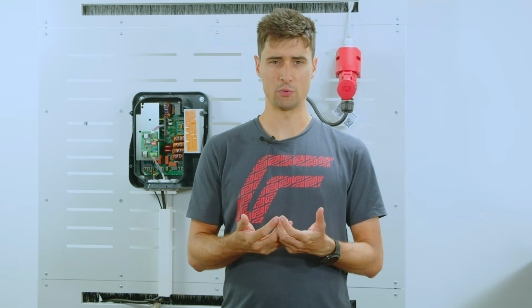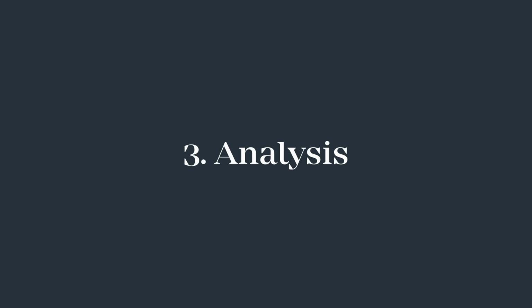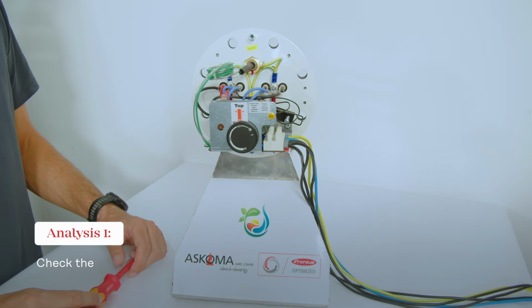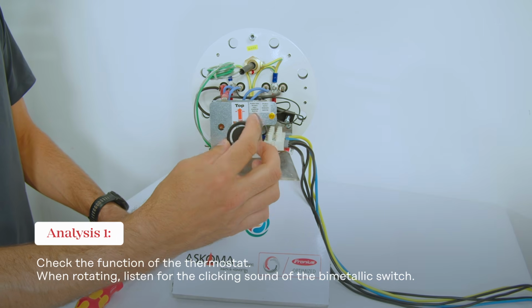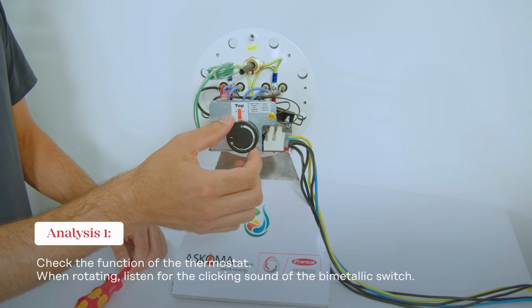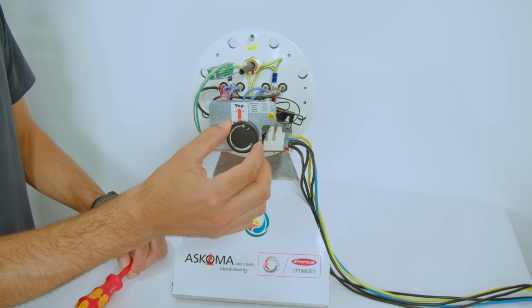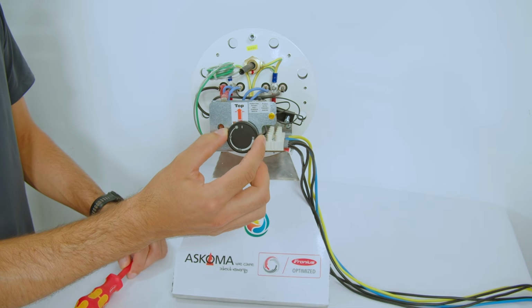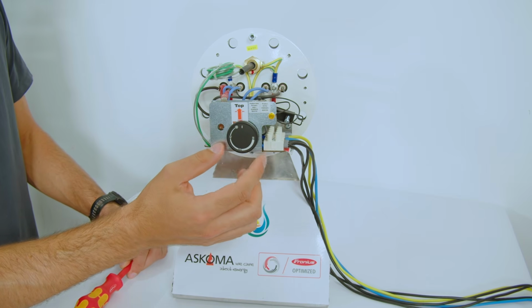We are now through with the easy wins, and if all that didn't help, then we go to the step-by-step analysis of all components. We will start with the heating element. First we check the temperature sensor of the heating element. In order to do so, we navigate to the temperature maximum first, and then go slowly back to minimum. If the temperature sensor is working, then you should hear a click noise. This click noise means that the bimetal switch is turned off and that the temperature sensor is working.